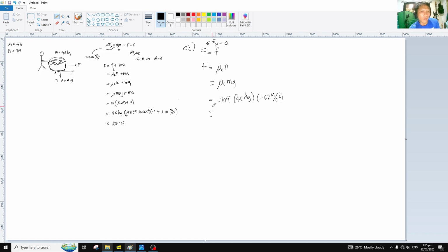So you would have that frictional force, the push to counter that friction. So this would be smaller. You can expect that this should be smaller because the gravity pull is small. So that should give us 51.7 Newtons for the push.